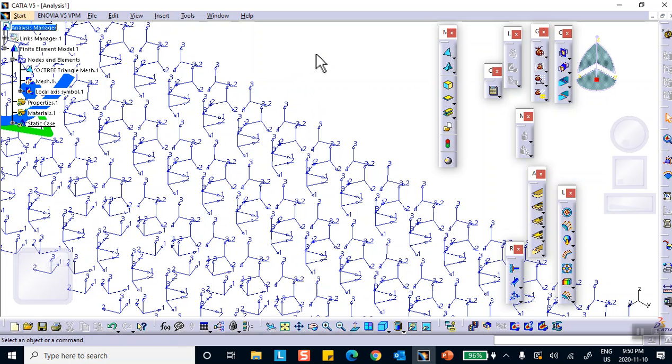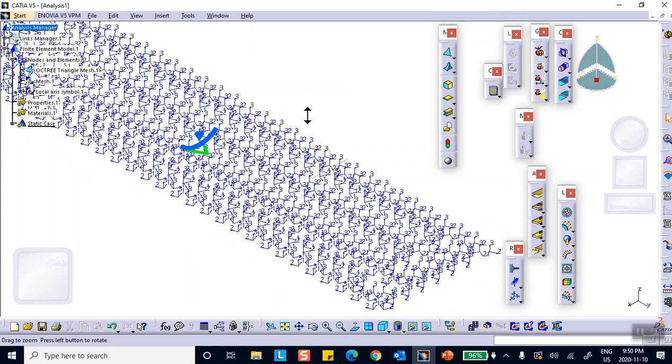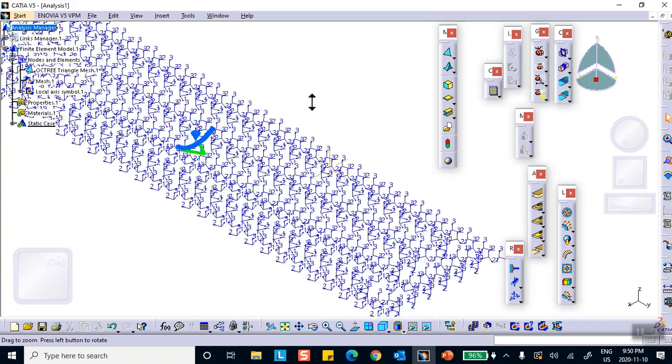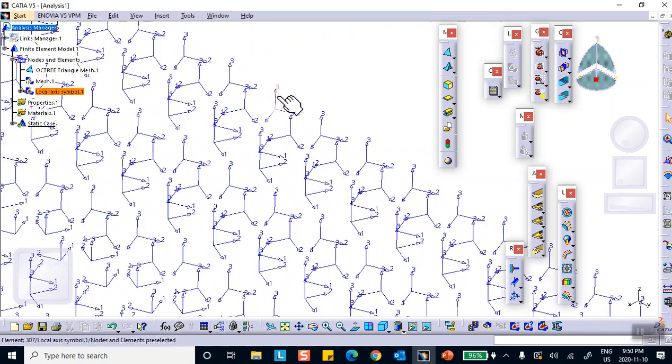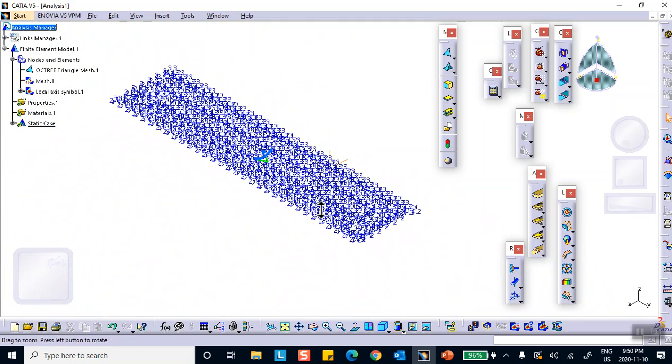up. Okay, and why I did this, because when I say rotating about the z-axis, remember one of the coordinate system was rotating about the z-axis by -30 degrees. Now that means that the 30 degrees that I'm referring to is with respect to this z-axis, which is also pointing up. Okay. All right. So you can display the local coordinate system for each element by creating this image.